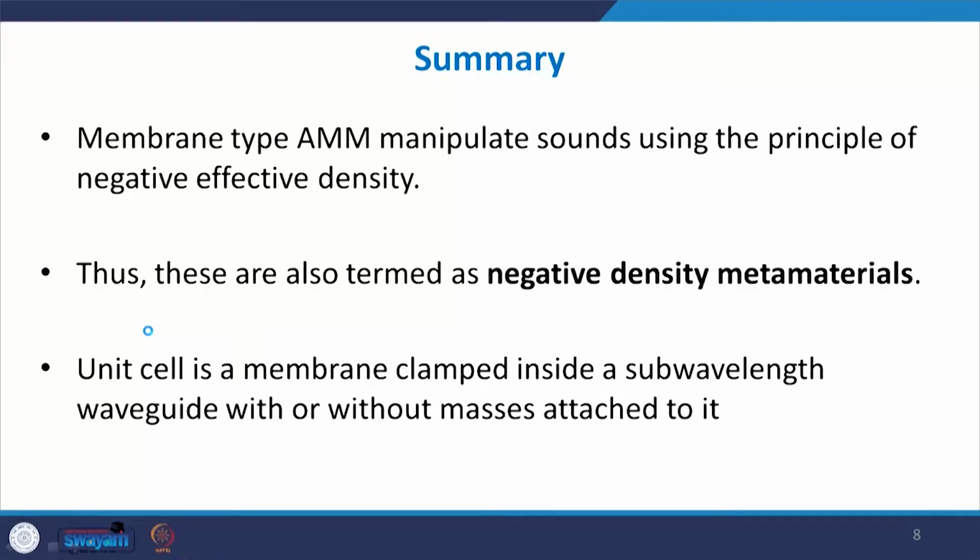So, a brief summary before we go into the advantages and applications is that such membrane type of acoustic metamaterials, they can manipulate the sounds using the principle of negative density, and that is why they are termed as negative density metamaterials. And the unit cell is either a stretched membrane clamped inside a sub-wavelength waveguide, either with or without some mass attached to it.